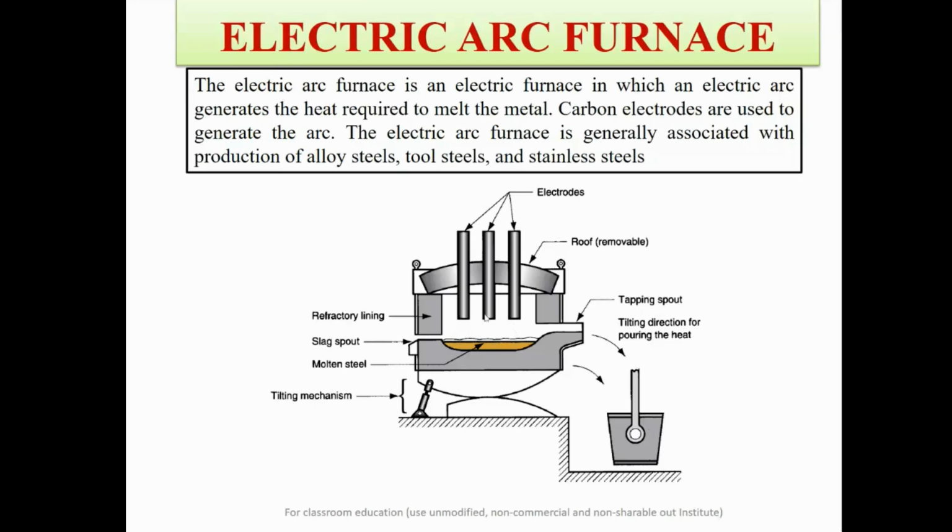So it results in the generation of an arc between the tips of these carbon electrodes, and this arc is of very high temperature, and an enormous amount of heat is liberated on the surface of your scrap metal, which causes the melting of the material.